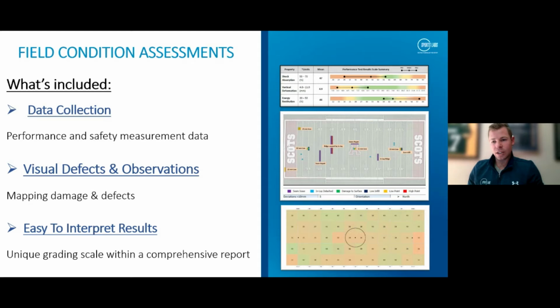So Mark, we've got the actual physical test, shock absorption, so a player surface interaction test. We've got numbers that are 55 to 70. That criteria is being taken from a tried and tested standard that's out there. I think the FIFA standard was brought into play in 2001, so it's been around for a long time. And then we've got the physical number that you've measured on the field, and that number's 47, so it's lower than the lowest limit, which is 55. So that's not good, is it?